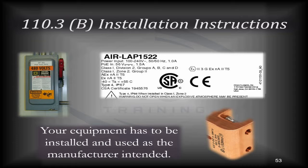110.3(B) pertains to the installation instructions. Your equipment has to be installed and used as the manufacturer intended. Again, as we spoke about just a short while ago, if the manufacturer's instructions are different than what the code says, and following the code would potentially violate the manufacturer's installation instructions or the UL listing, then chances are you're going to get a pass on that. But it's always important to make sure that you understand where your code official stands on the subject.